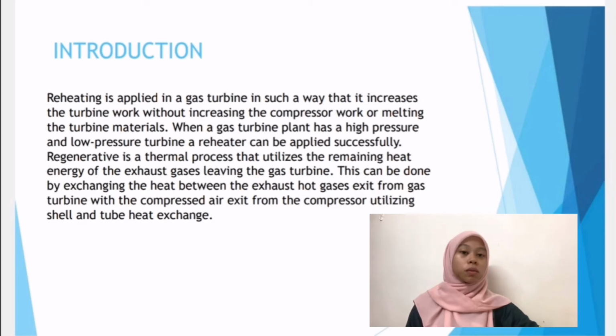Regeneration is a thermal process that utilizes the remaining heat energy of the exhaust gas leaving the gas turbine. This can be done by exchanging the heat between the exhaust hot gases exiting from the gas turbine with the compressed air exiting from the compressor, utilizing a shell and tube heat exchanger.